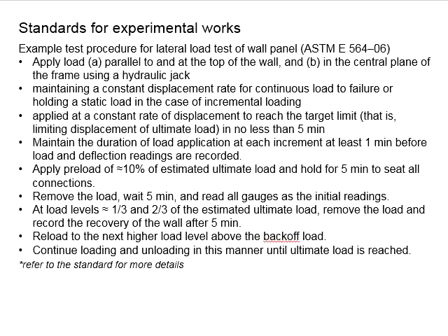You need to apply preload of about 10% of the ultimate load. Hold for 5 minutes to seat all the connections. This is a precautionary procedure to exercise the specimen and settle everything within the test setup, so that whichever readings are acquired during the testing later will not be due to the settlements of some connection joints within the test setup.